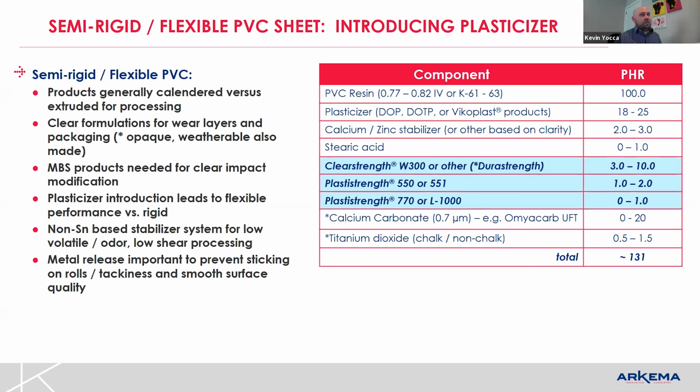What I say we typically watch for in our lab when we do testing is, I want to know what the bulk density of the compounds is, just because our customers all have such different formulations. I want to make sure that I have an idea if something's really out of whack. If somebody's at 58 grams instead of 65 for their window profile formulation, geez, that's different. We should make sure we monitor that when we're testing specifically for them. Maybe let them know that we see that's different. Is there any idea why?